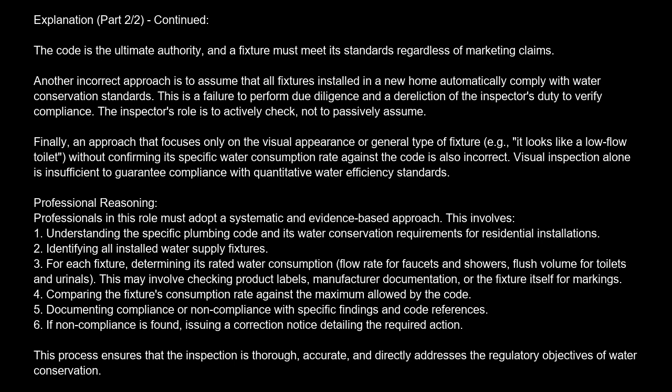Finally, an approach that focuses only on the visual appearance or general type of fixture, e.g., it looks like a low-flow toilet, without confirming its specific water consumption rate against the code is also incorrect. Visual inspection alone is insufficient to guarantee compliance with quantitative water efficiency standards. Professional reasoning. Professionals in this role must adopt a systematic and evidence-based approach.